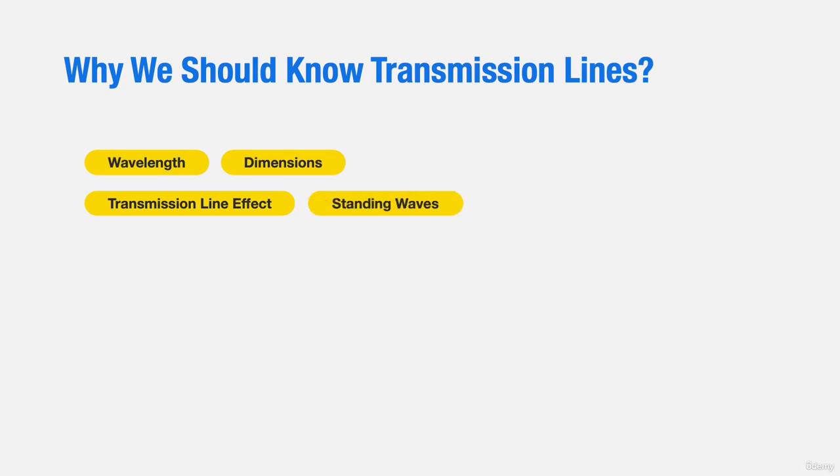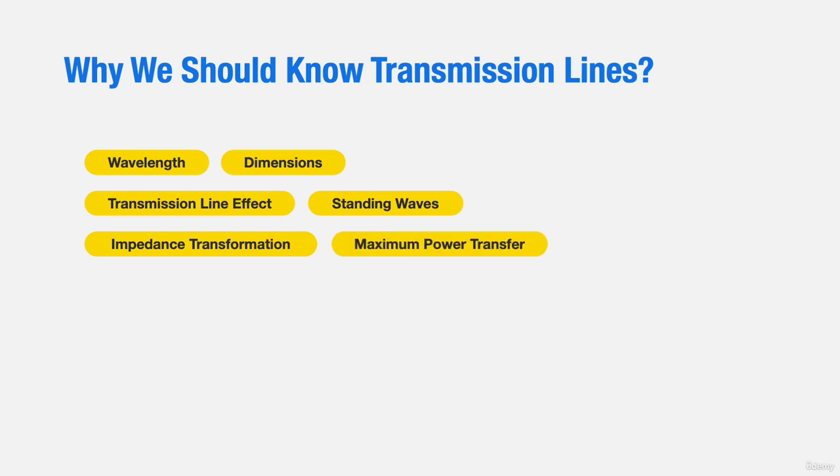This effect can cause the load impedance we expect to be, for example, 100 ohm, to be converted to 300 ohm or 500 ohm, or even a complex value impedance at a certain operating frequency. As a result, the circuit may not meet the original design requirements. This effect is directly related to frequencies. The higher the signal frequency, or the longer the line, the more apparent the transmission line effect becomes.